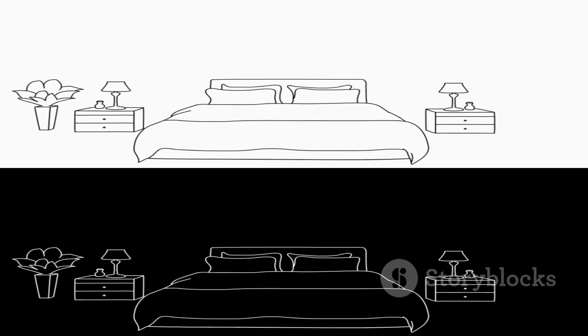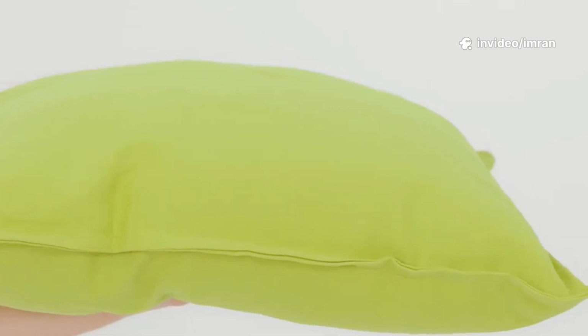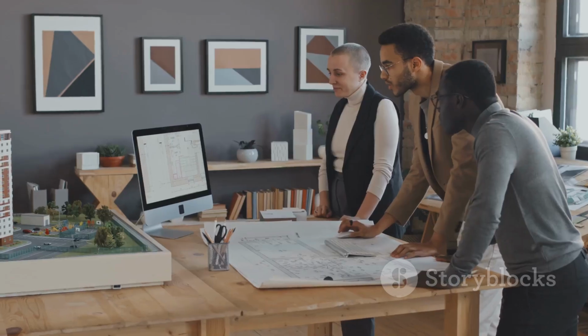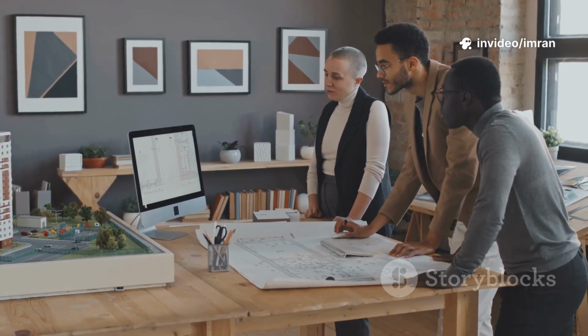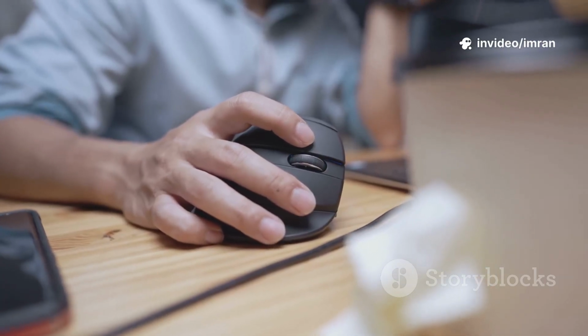Let's create a simple bed. A standard single bed is approximately 2,000 millimeters long and 1,000 millimeters wide. Use the rectangle command, Rec, and create a rectangle with those dimensions. Now, create a smaller rectangle for a pillow, and place it at the head of the bed. Group the bed frame and the pillow together, so they act as a single unit using the group command. Use the move command M to place the bed against the top wall of the room.